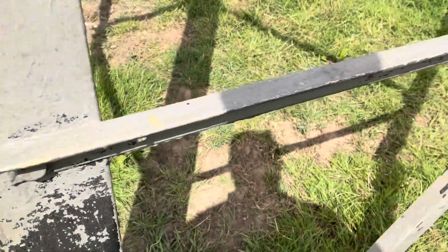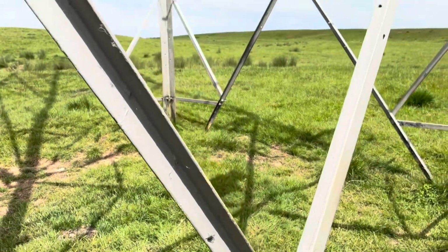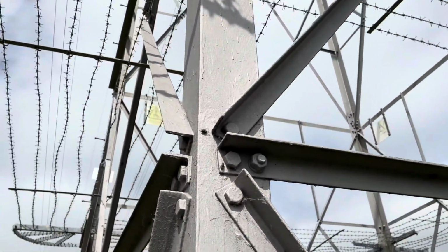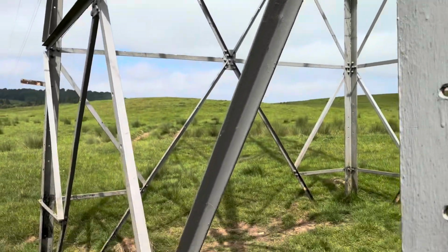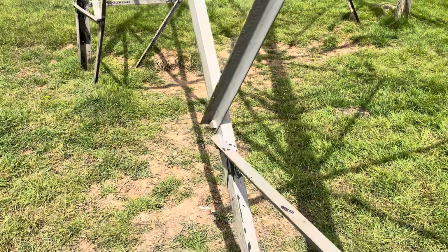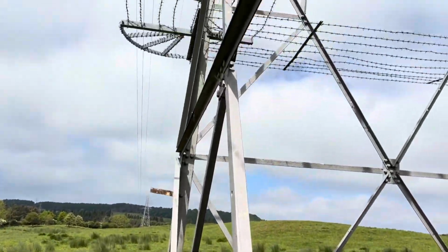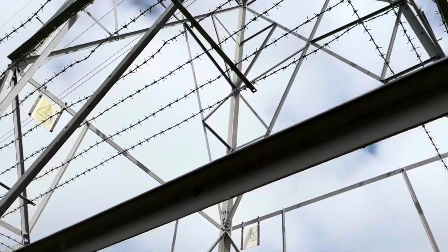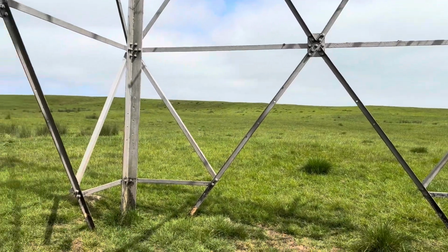So we're just doing a few close-up shots. This is called a visual ground inspection. Now, if I did spot any red flags, I then would advise the client to carry out a tower climbing inspection. This will consist of somebody actually climbing the tower, keeping note of all the bent, rust, and corrosion that they spot across the tower. And then we'll be able to take this information back to the client and advise them on what to do next. Do we either strengthen it before we carry out our design work, or take it into account during our analysis work?